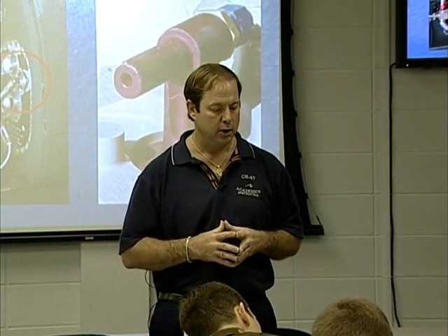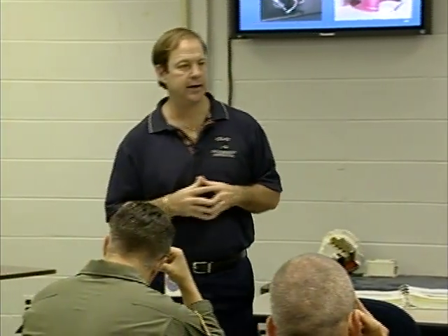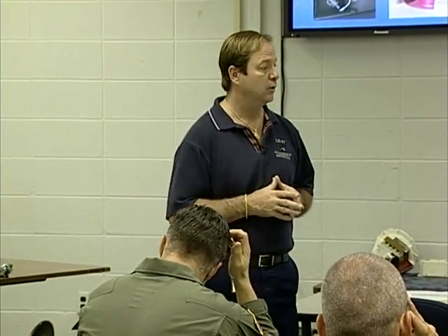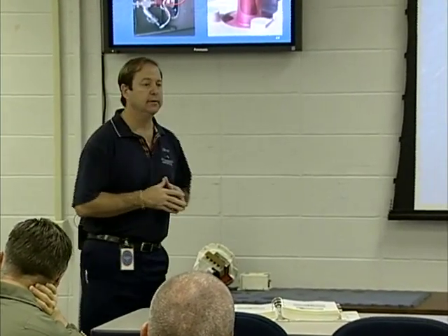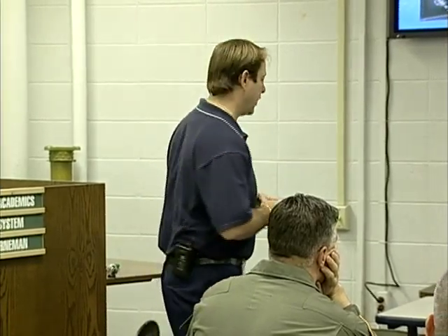Agreed? So what's going to happen is in the forward intertank area associated with the forward main pump of each side, we have what's called a jet pump for the process of evacuating fuel out of that line. Now, if anybody's ever had a waterbed and you've had to empty it out, you're familiar with this process. It works on the same principle. So what is that principle?